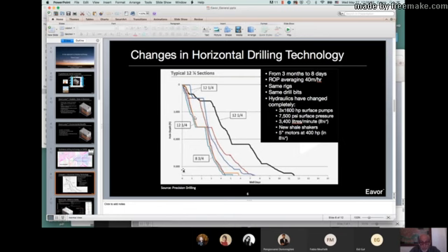So a 9 kilometer deep well with shale gas technology, you can drill it in about 9-10 days, which means you go a kilometer a day. It's a technology that is totally different. It runs on very high pressure mud and is so efficient that you can be so fast.